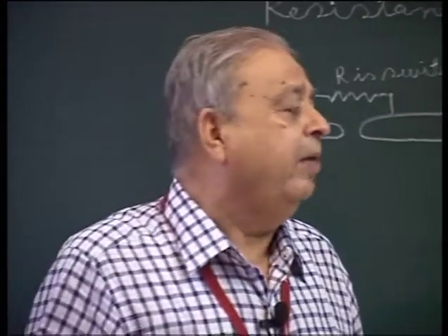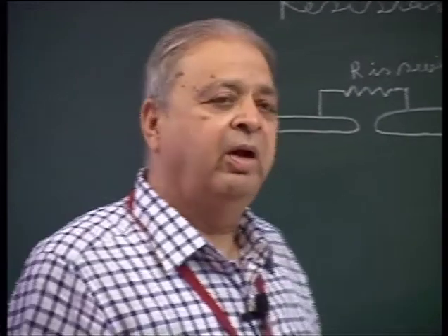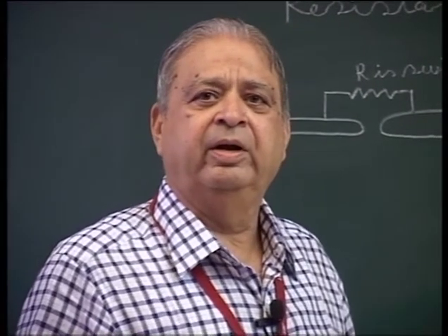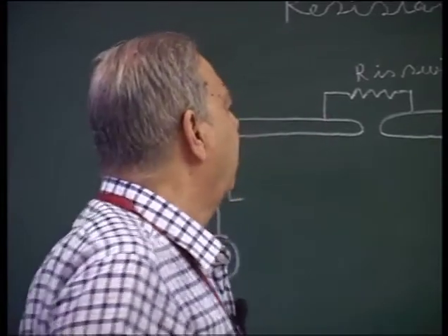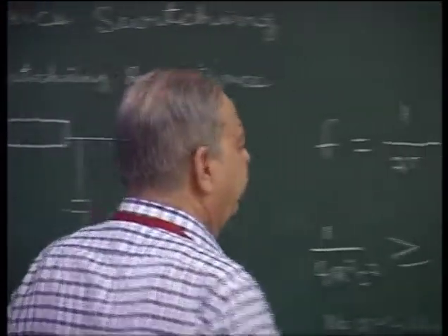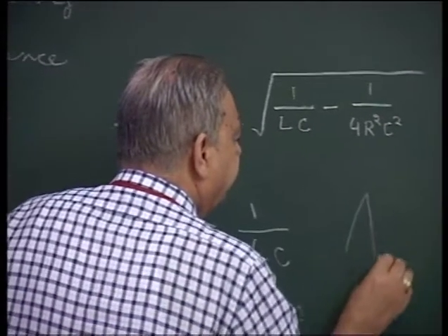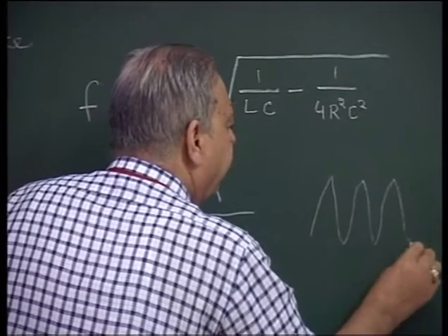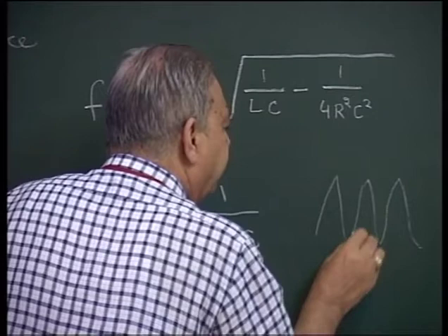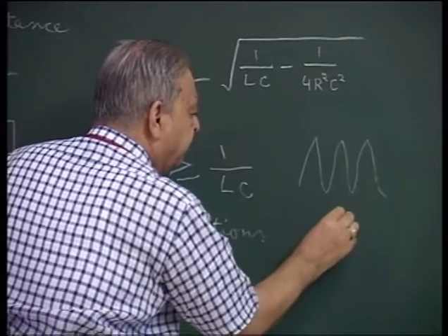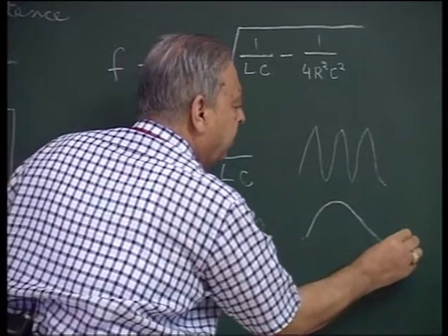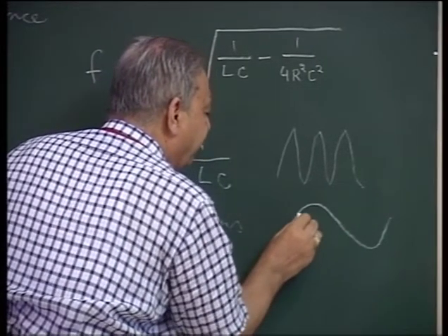And high frequency transient oscillations are the bigger culprit in restriking the arc. Because when the voltage is varying very quickly at high frequency, the rate of rise becomes very high as compared to the 50 cycle voltage, where the rate of rise is very low.